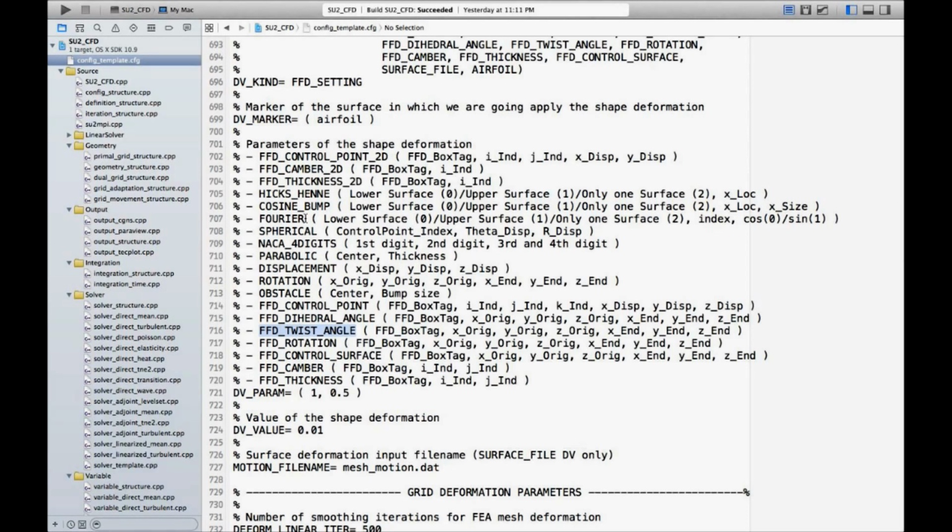We have a question from Vinoth. So the question is, as far as I have explored, SU2 is taking only the cell neighbors, so the nearest neighbors, for the least squares gradient calculation. So 4 neighbors in the case of 2D quads. For my application, I need to calculate the gradients, and I would like to use the vertex neighbors, so I guess neighbors of neighbors in this case. So is there any option to get the vertex neighbor data, another function to get access to that?